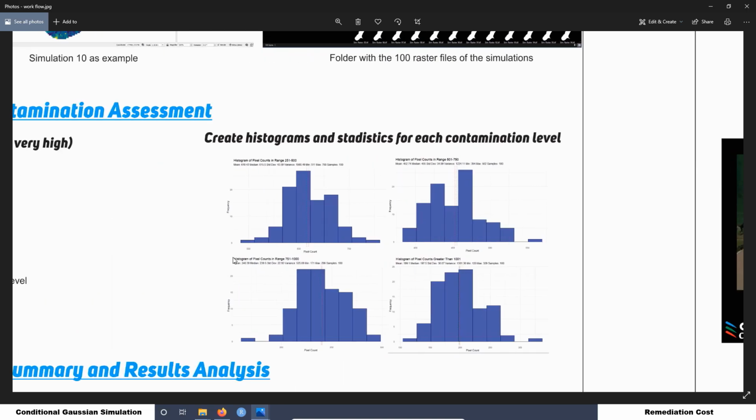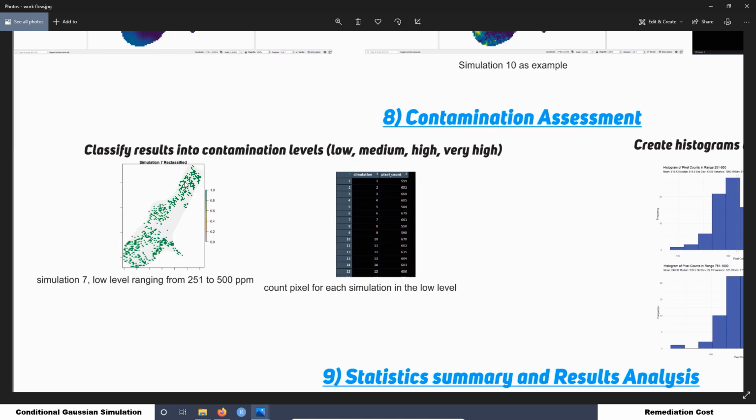However, today what we are doing is learning how to do this process using R, only R, and also we are going to see how we can make a quality control with QGIS using both softwares. You know, calculating the classification of the soils using R and also calculating the classifications of the soil using QGIS. Then we can compare the results and we need to have the same results. And if we have the same results, we can say that we pass the quality control for the classification of the soils according to a specific range of concentration.